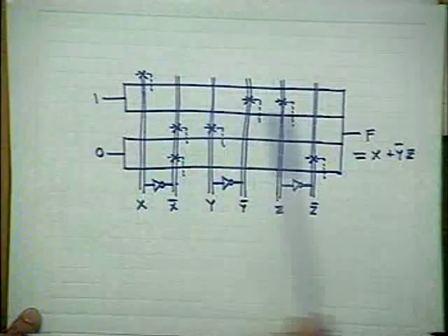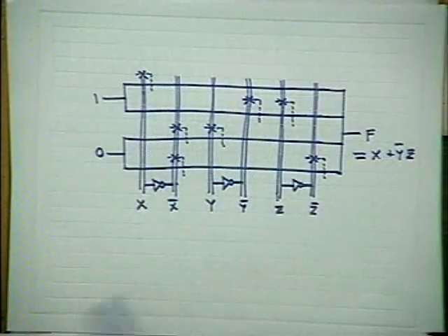Entirely a structured logic. Realization is rather simple. What you have to do is called personalization of the array. You have formed an array of horizontal rows, here rows of diffusions and columns of metal lines, and then at appropriate locations you have cross cuts called via holes, small vias, and short poly. That means the mask should contain that.